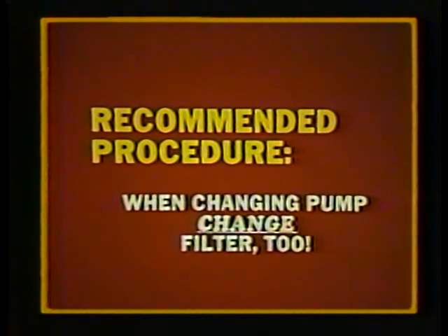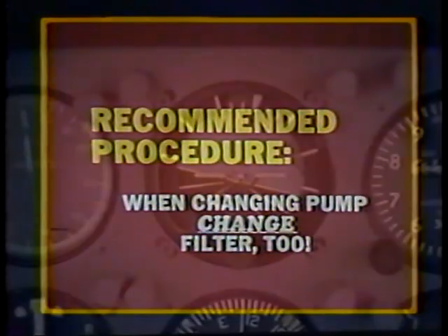In the event of pump failure in a pressure system, be sure to replace the inline filter as well as the pump. The reason for this is the possibility that small, sharp carbon particles from the old pump could be discharged into the system, and with vibration and time, the particles could cut through the paper filter element and cause damage to the gyros.